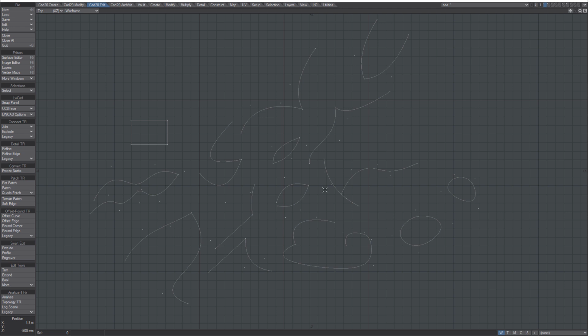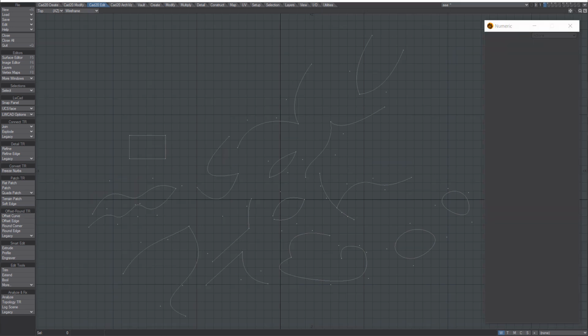Offset tool in LightWave 2020 is completely updated from previous version, which is still available in legacy folder here, and it is updated to two new separate Mesh TR tools, offset curve and offset edge. The reason of this split is to get user more control about offset operation on different geometry types.